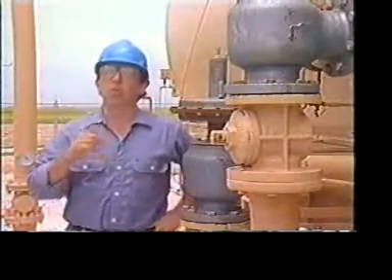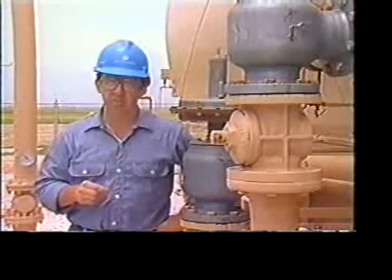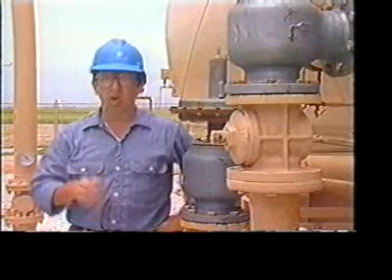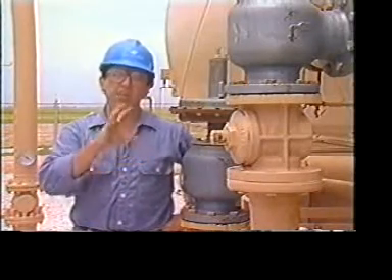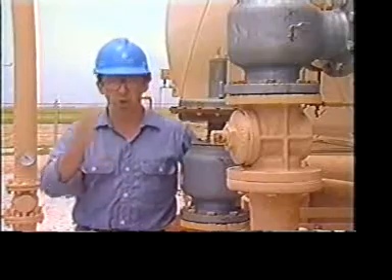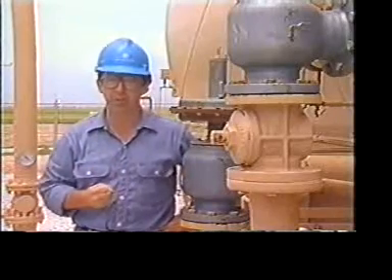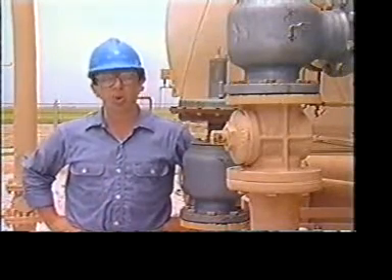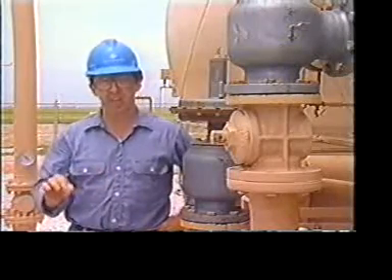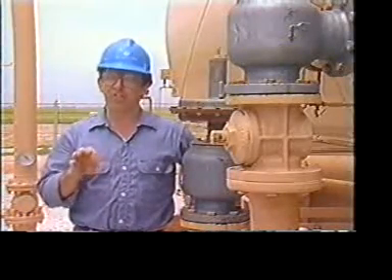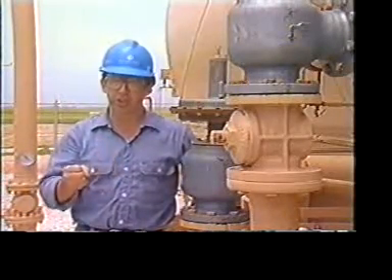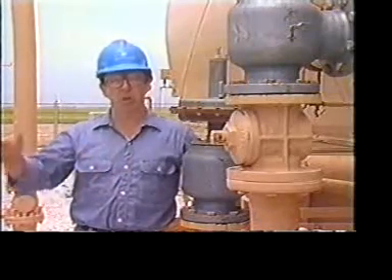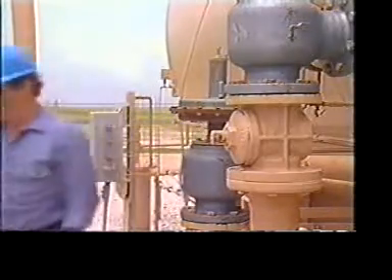Finally, if you're having problems with oil in the water disposal system, this can result if the oil outlet is plugged, or the oil dump valve is stuck closed, or the water dump valves are stuck open. Sometimes when the oil outlet on a treater is below the oil inlet on the lease tank, and the back pressure valve fails to hold a positive pressure on the treater, oil will go through the water outlets into the water disposal system.